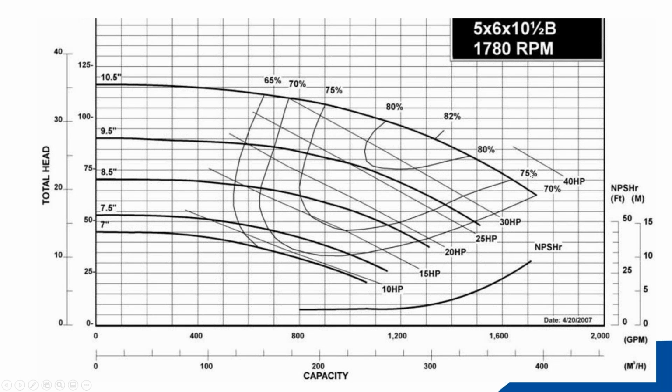But if you remember, that other pump curve I just showed you was just a single curve, right? It wasn't like this topographical map. Well, you can still make a curve out of this because you can say at a single impeller size, 65% efficient lands me at about, what is that, 4, 5, 650 or so. And you can create your own curve, which is what I have done.